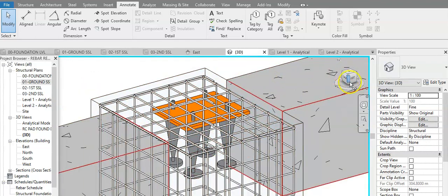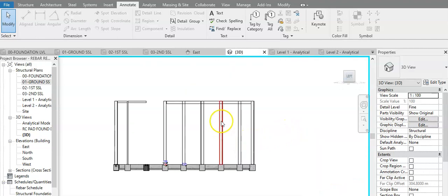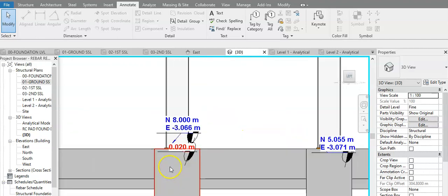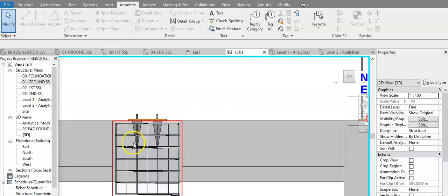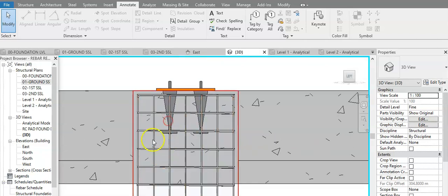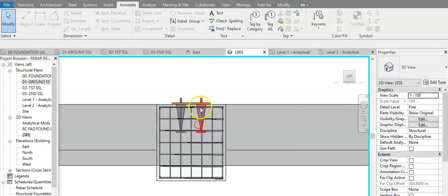And if you look at it from the side elevation or side view, you'll see it becomes like that, where you see the reinforcement and the holding down bolts fixed into the reinforcement way down, and part of it they call the projection, where the steel frame will sit and penetrate through these holes.